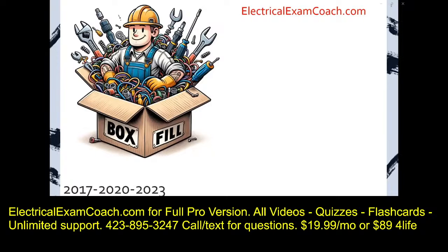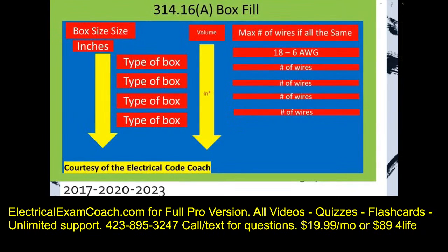Hey everyone, welcome back. I am the Electrical Code Coach from electricalexamcoach.com. This is lesson 6.1 in our video series. Today we're going to be learning all about box fill. We're going to be in section 314.16, and we have two primary tables that we're going to be using. The first one that we're going to cover is 314.16(A). Let's get to it. On the left-hand side is going to be our box size in inches.